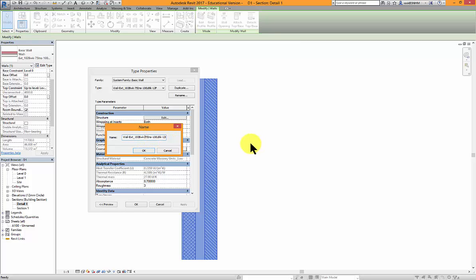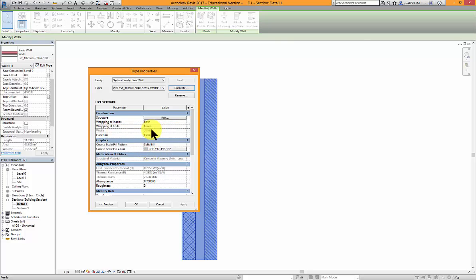So let's add brickwork, then 50 air, and then let's change this insulation to 85. Then delete number 2 at the back, and also the blocks, instead of 100 I would like to use 120. Then OK. Then we have to change our structure.